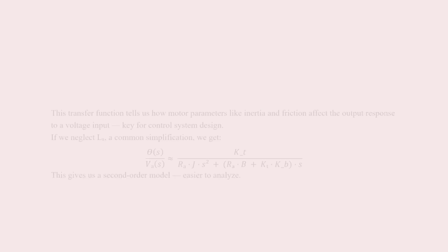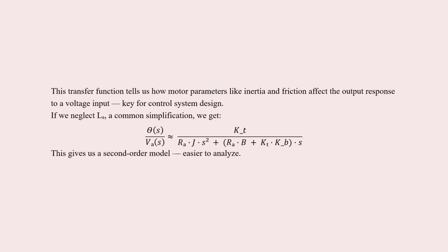The next one is about the transfer function. Sometimes we need to make a simplification, so we neglect La, that means the inductance. Mostly the inductance of motors is very small, so we neglect it. Then the inductor based equation is eliminated, and the system is considered a second order system, not a third order system. Then, to analyze the effects of resistance changes, voltage changes and position changes, they can easily be identified.